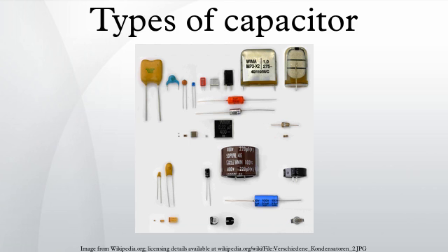The types of capacitors used for power applications have a specified rated value for maximum ripple current. These are primarily aluminum electrolytic capacitors and tantalum, as well as some film capacitors and Class II ceramic capacitors. Aluminium electrolytic capacitors, the most common type for power supplies, experience shorter life expectancy at higher ripple currents. Exceeding the limit tends to result in explosive failure. Tantalum electrolytic capacitors with solid manganese dioxide electrolyte are also limited by ripple current. Exceeding their ripple limits tends to cause shorts and burning components.